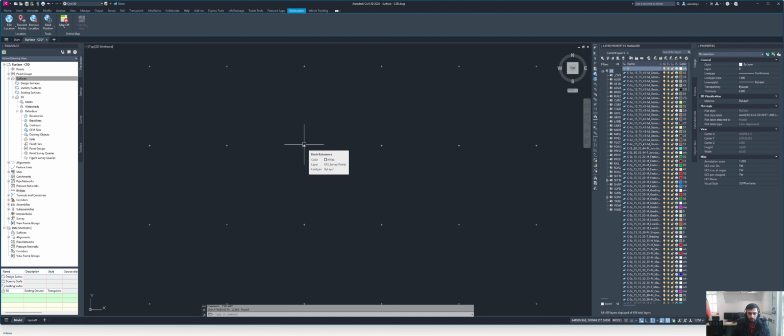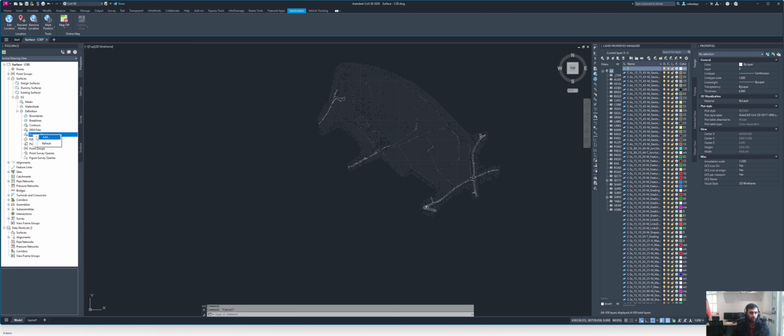If you click on any of these points, you can see that they have the X, Y, and Z geometry, so these can easily be used in our Civil 3D surface. Everyone has their X, Y, Z geometry, but they are block references. So I am going to definitions, click on the drawing objects, right click, add the drawing objects. You will see this is points.